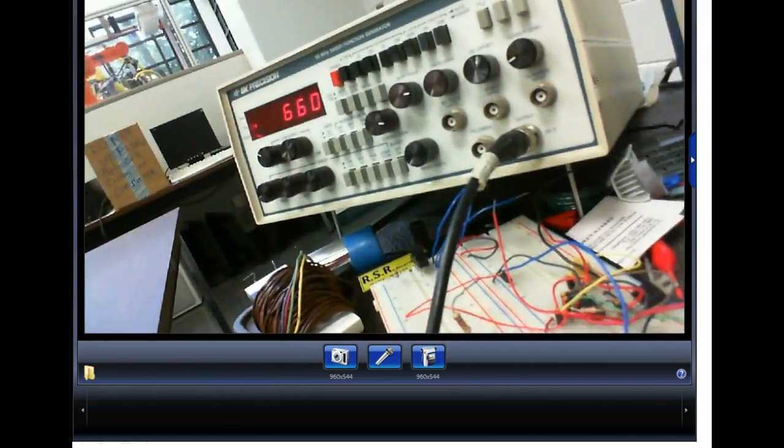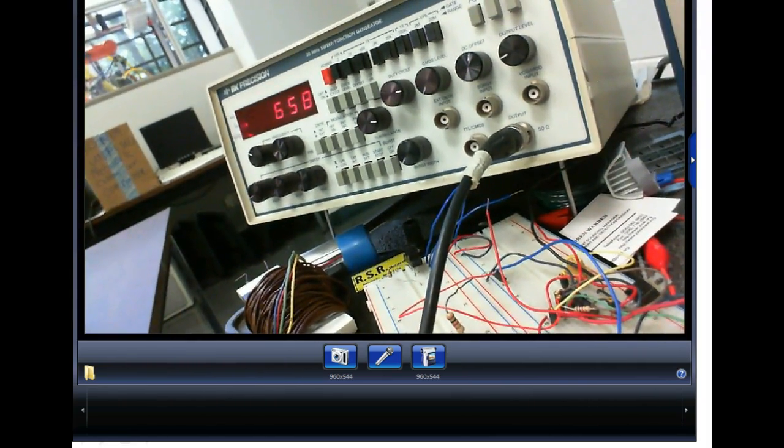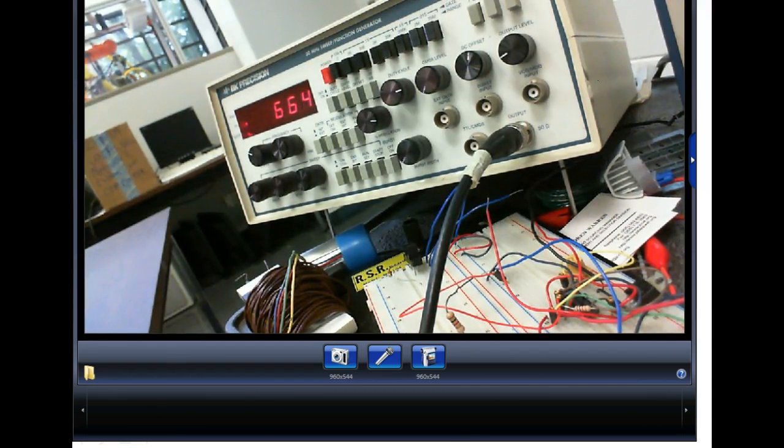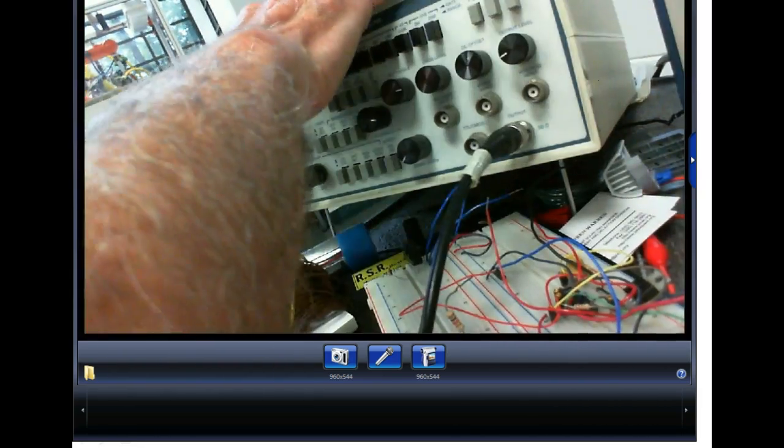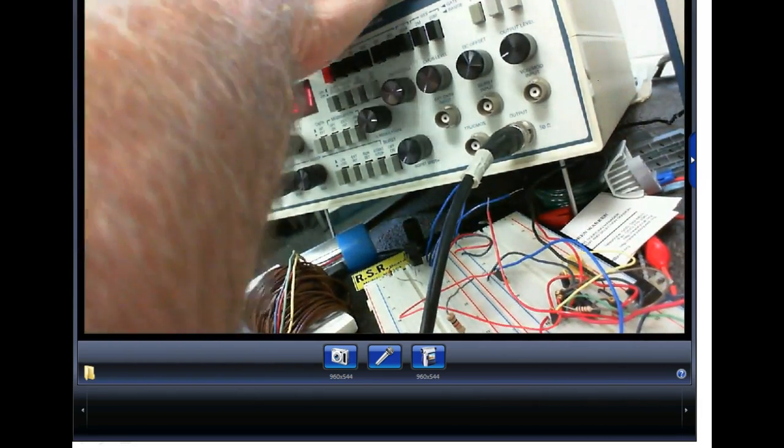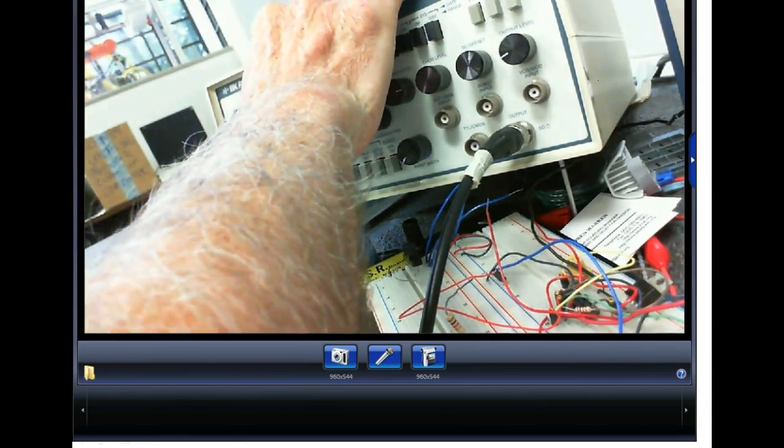We're not going to be using a function generator much in this class. Most of our stuff is going to, that's not true. When we get into transistors, we're going to use DC to power the transistors up, and then we're going to make them amplify stuff. And we're not going to let them amplify Alabama Power. We're going to let them amplify signal, right? You understand? So we're primarily going to use this guy to generate the signals. This is not considered a power source. It's considered to be a signal source.